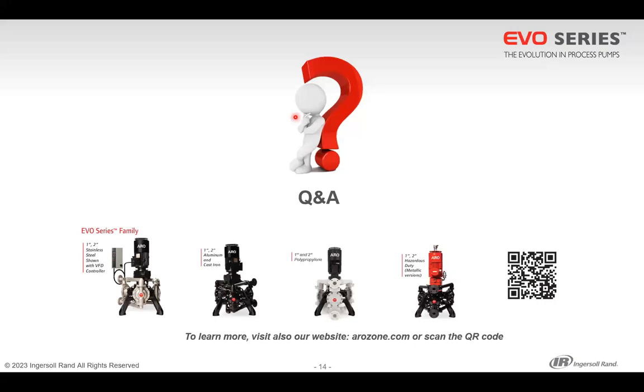850 kilograms per cubic meter. This is, I think, again, regarding the PTA powder. 850 kilograms per cubic meter is within the possibilities of the powder pumps in general. Now, as I told, it's not the only information we need, but it's within the possibilities. What I'm still concerned about is the quantity. I mean, 40 tons per hour requires a lot of pumps.